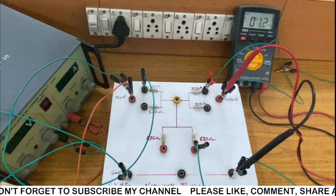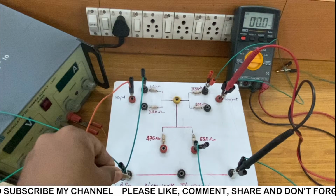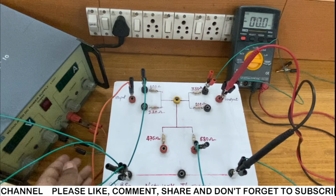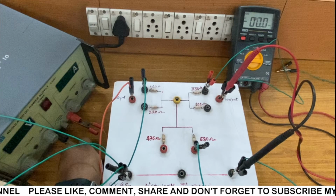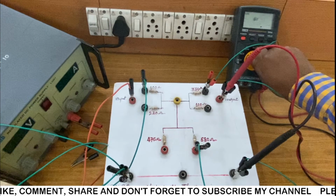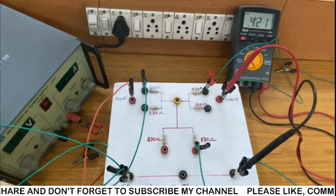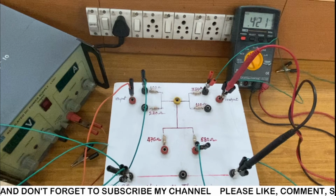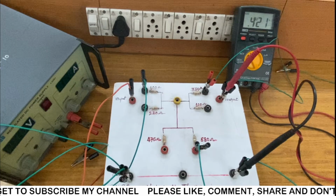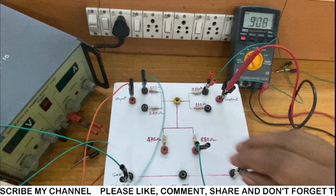So to measure RTH, I have to just disconnect the power supply and I have to short the R1 with R3 so that the supply is just removed, and we are going to measure the equivalent resistance or RTH. So I have to make it to resistance terminal, 0.421k. So it is 421 ohm actually, or we can say 0.421 kilo ohm. So this is the way we can measure VTH and RTH for one combination.